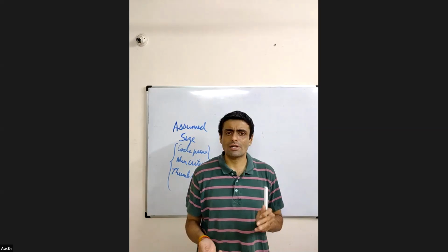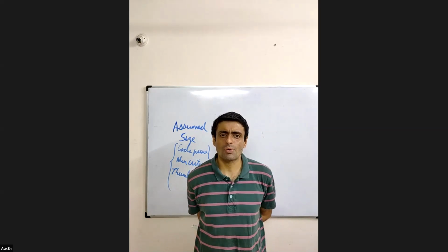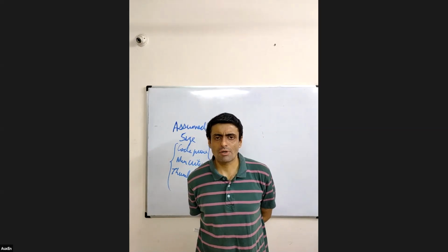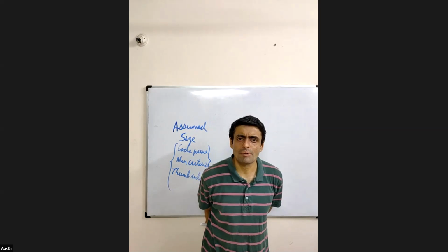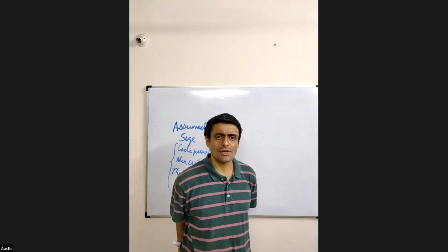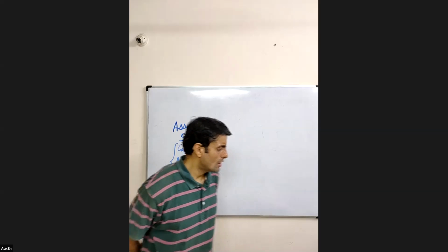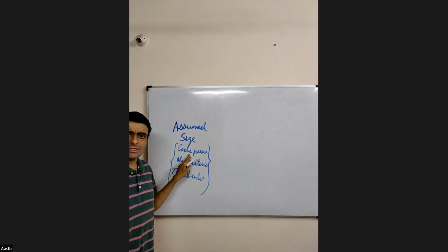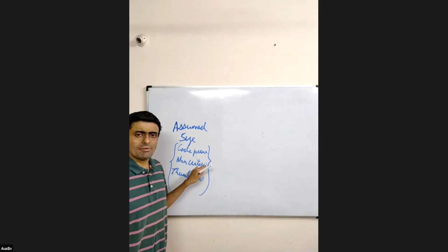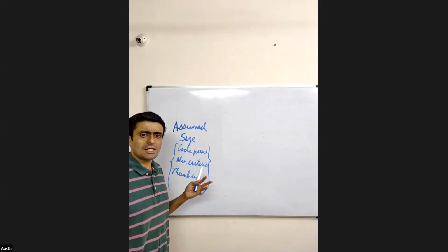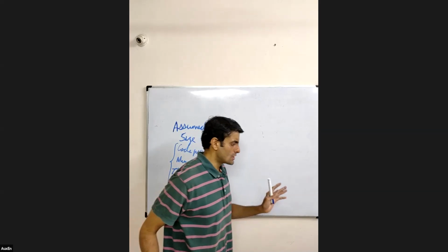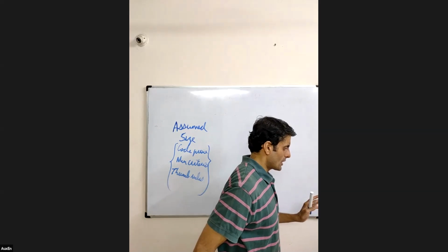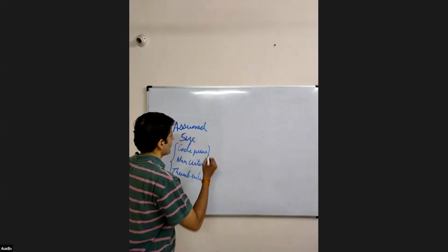Let's say our code tells that you have to provide a minimum beam width of 200 mm, or let's say our code says that you have to provide a minimum slab thickness of 125 mm, for example. So you have to start with some codal provisions that are given to you, or some minimum criteria, or some thumb rules that are available to you. So this is your starting point. Okay, this is your starting point.